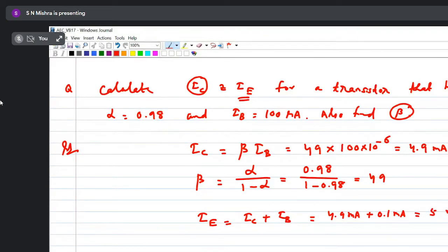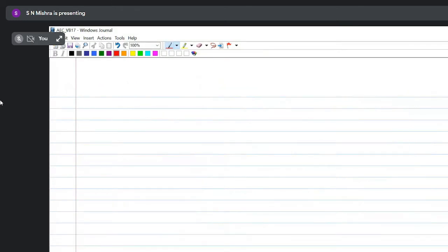which will pass through this FBG4, that is fiber Bragg grating 4, because this fiber Bragg grating FBG4 is blocking lambda 4. So it will pass lambda 1, lambda 2 and lambda 3. From this port, lambda 4 is coming. It is being circulated to this, and when it is coming, it is being reflected back.